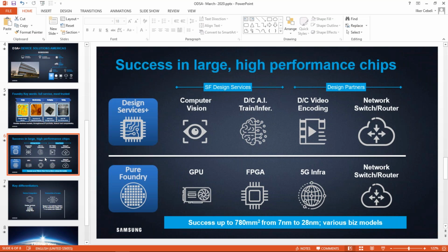So we are in very early stages. Even though we, as Samsung, made significant advances in the HBM area, and we have a lot of learnings from HBM, we are on the 3rd generation now, so we totally understand silicon interposer packaging as well as the interfaces. But I think the challenge, from what we are looking at from ODSA, is how much standardization we can get between the protocols and the interfaces.